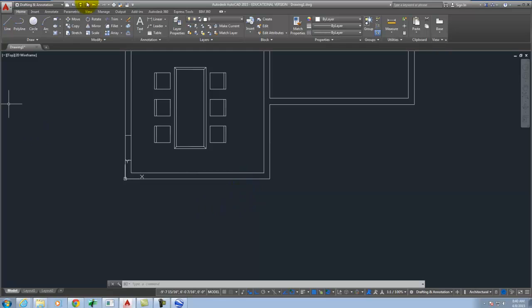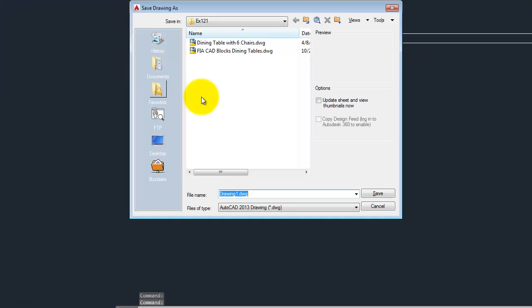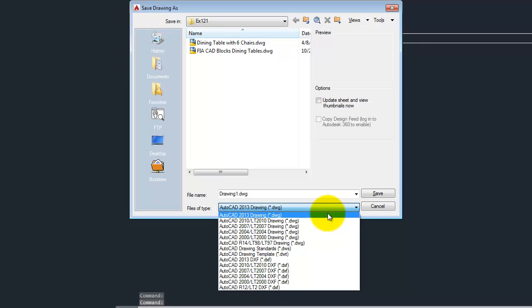If you do need to go backwards, you can click on Save As, and it'll tell you, yeah, it looks like 2015 goes back to the 2013 format, right? If you need to go back further, just do a Save As and do 2010. So you can see 2013 is one, 2010 was another, 2007 was one, 2004 was a big one, and then 2000. So you can see that they jump every several years. So just save it back as...